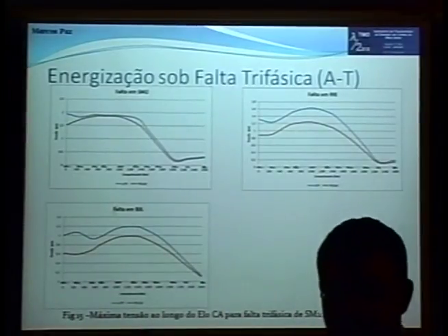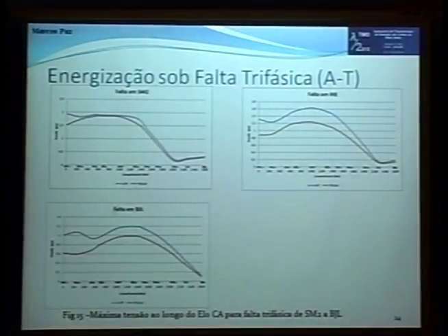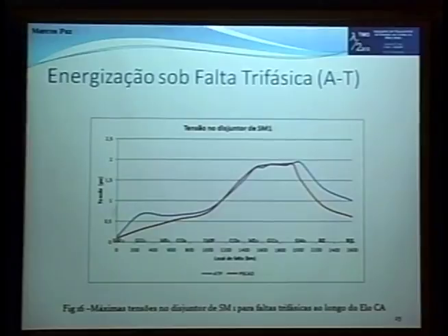From this point on, the overvoltages go down, and then we would not have the surge arresters working. And for the terminal fault located in Bom Jesus, basically we do not have considerable overvoltages in comparison to the values observed in the critical region.